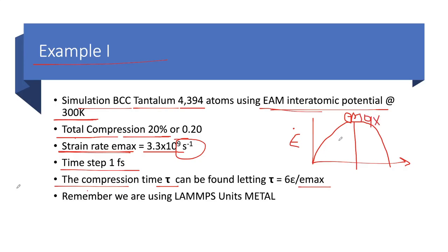Okay, and this is running from 0 to tau, right? So the only condition to compress something quasi-isentropically only depends on whether the epsilon at 0 and the epsilon at the final time that we define as tau are the same. In this case, it's going to be equal to 0. If that happens, we can deform quasi-isentropically.